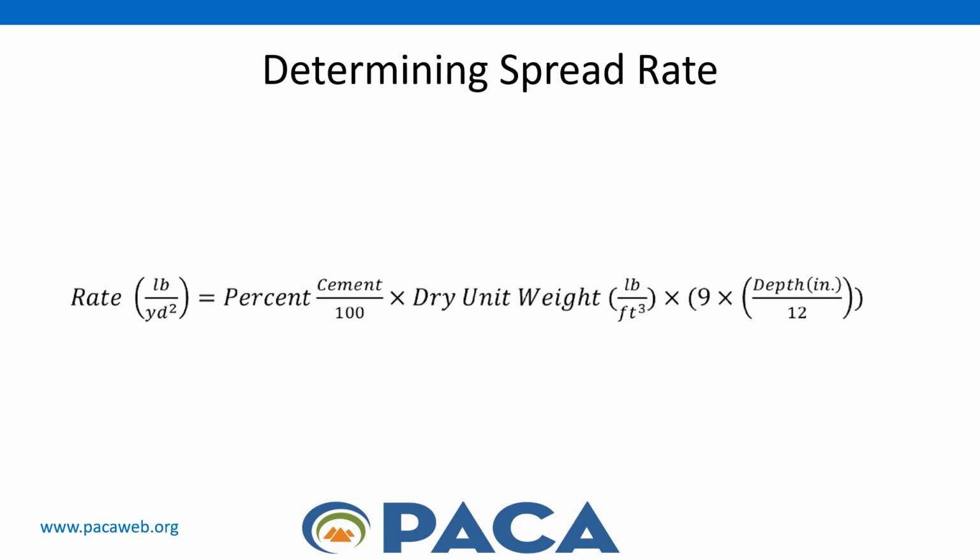Remember that the percentage of cement to add was calculated and confirmed in our mix design phase of the process. The dry unit weight and the depth of remediation were also determined during the geotechnical evaluation phase of the process.